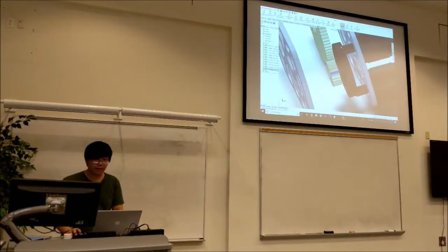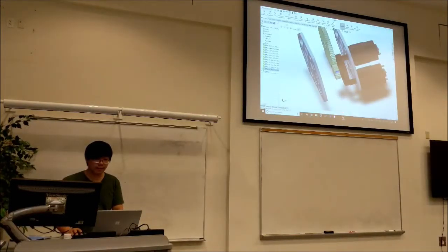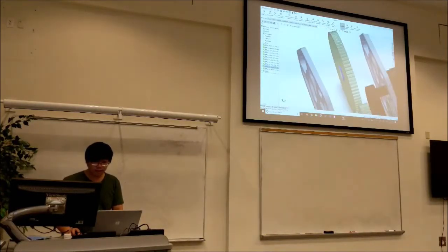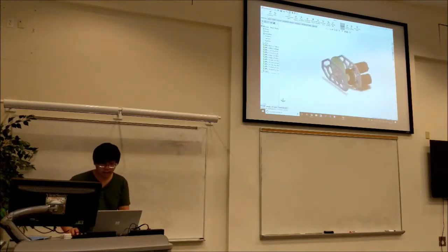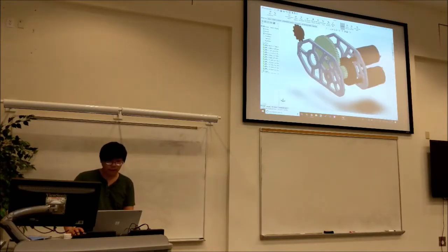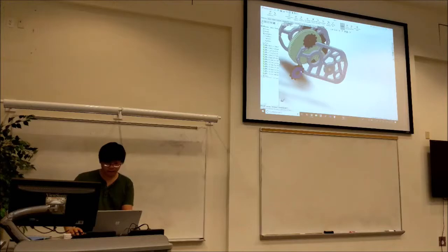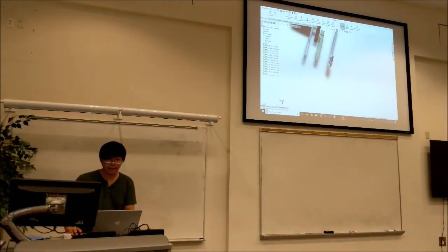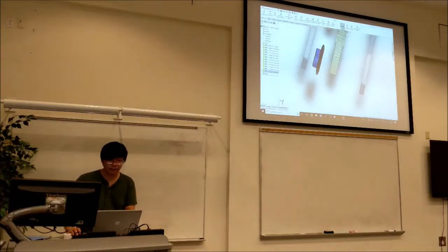So this is our first stage, right? From the pinion to this gear is our first stage, and then we have a second stage going from this to this. Then we can add a sprocket here. Again, imagine this is for an elevator or something. This chain can be used to drive our elevator up and down.